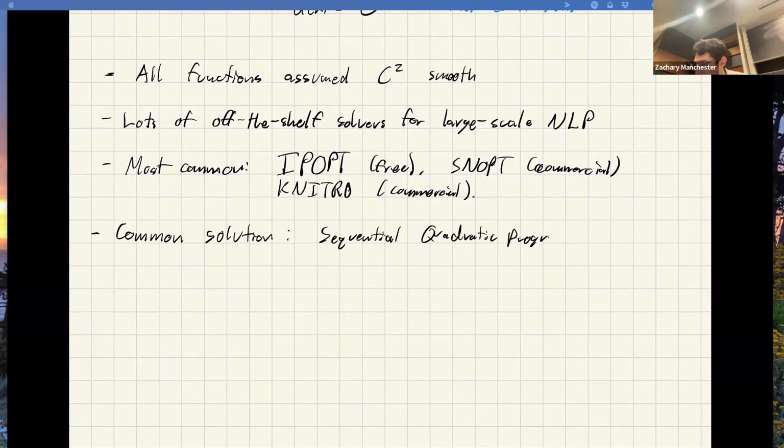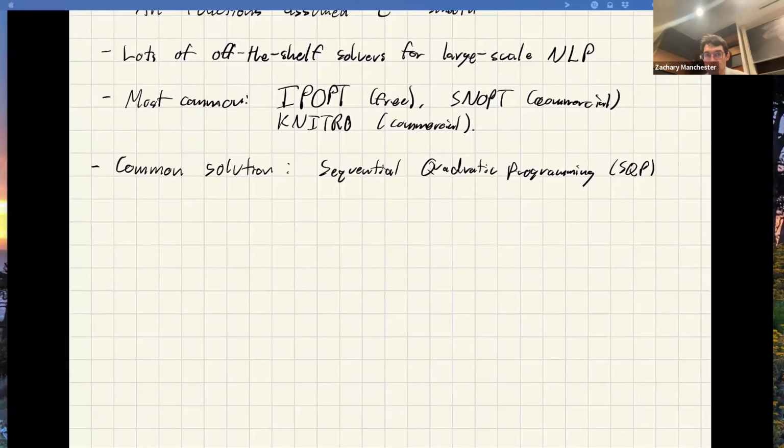Also, SQP is probably the most common technique for nonlinear MPC. Almost every nonlinear MPC implementation you see on a robot is doing SQP for various reasons. Some of them do DDP, iLQR stuff, but all of the direct versions pretty much do SQP.